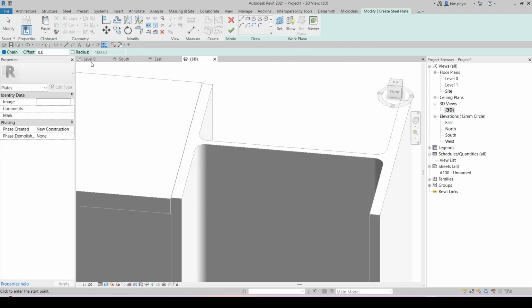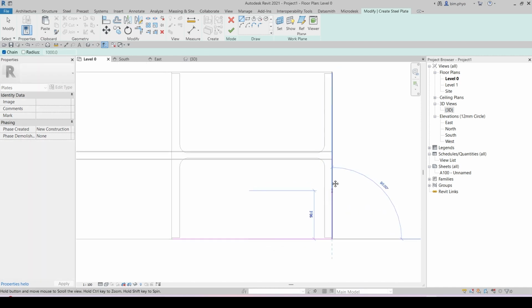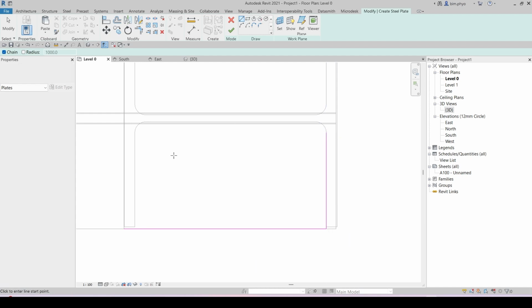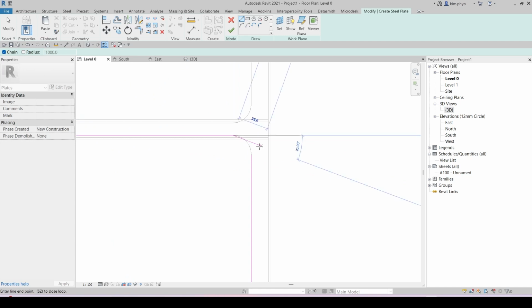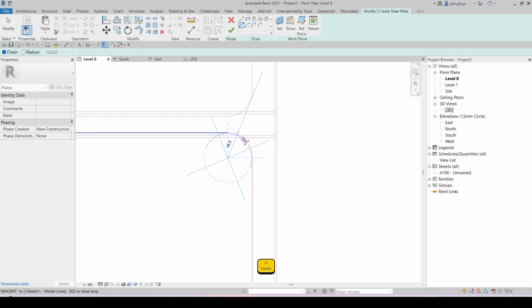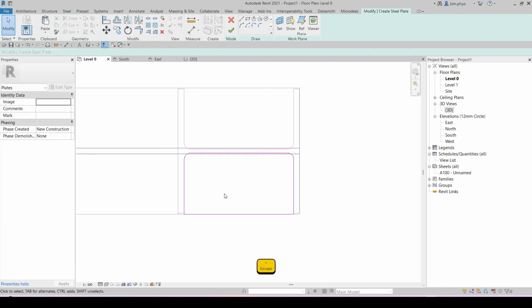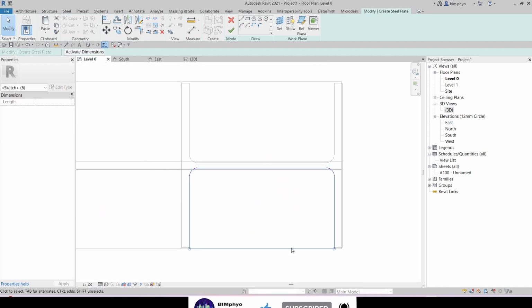This one I just place it, go into the plan view, and I will draw manually. And here, right over here, then the 3-point curve like this. Oh, not that one. It's like this and like this. So we have it. So in here, the biggest advice: if you don't mirror into there, the plate only allows one loop. It doesn't allow you another loop somewhere else. No, it doesn't allow you to create.